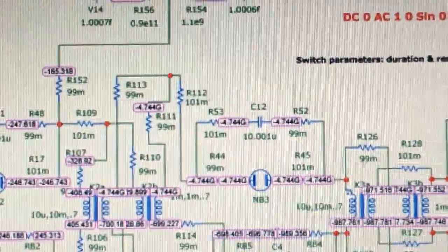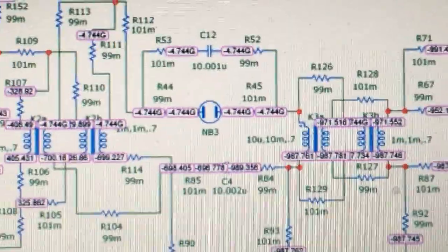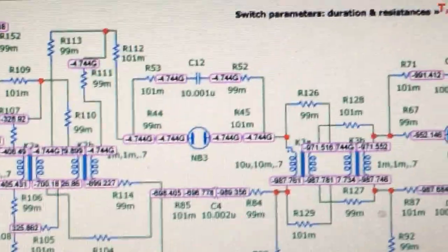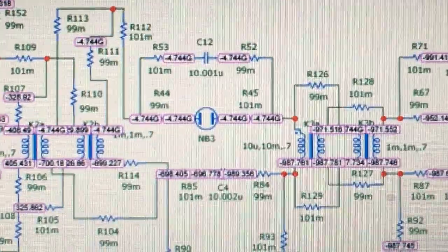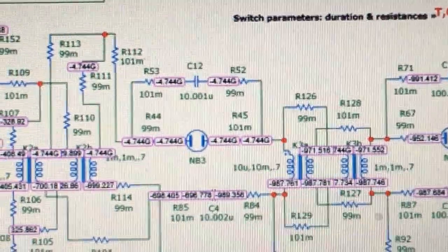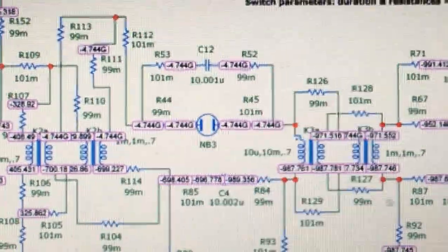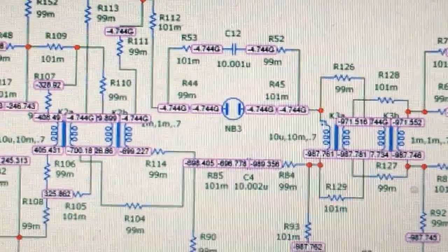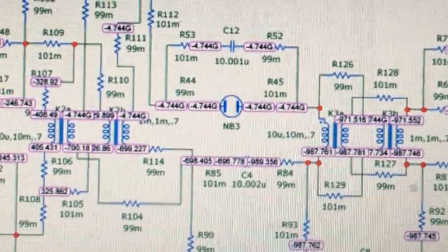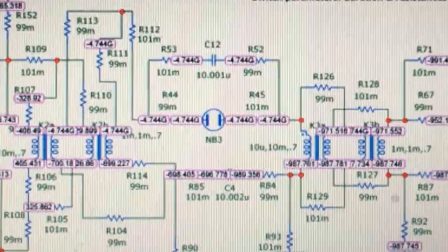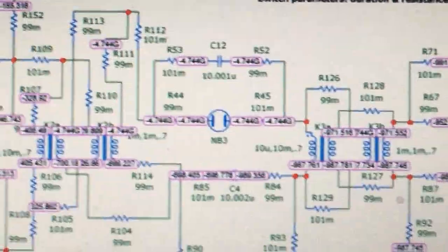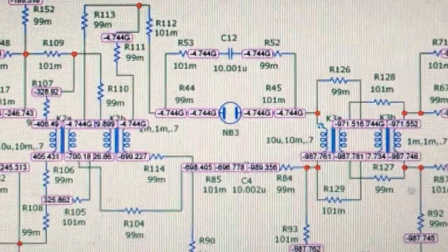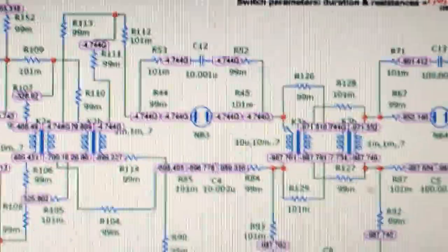The problem with that is that it makes the energy buildup in here escalate so fast that I can't regulate it. It literally blows up in my face. In fact, I have one version of this circuit in which the time frame for the transient analysis is 1e to the negative 100. And it literally goes to infinite gain and shuts down because it can't go any further. And you're stuck with an explosion in your face that is instantaneous. You can't even find out how fast it goes. It's so fast. So I don't like LTSpice for that reason.